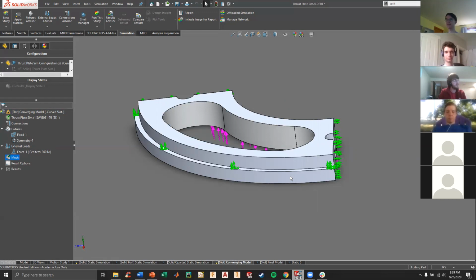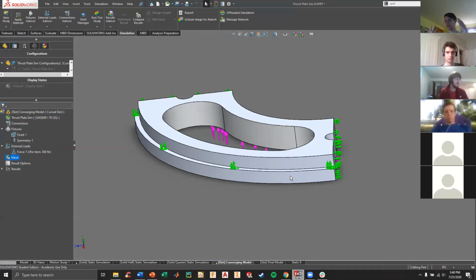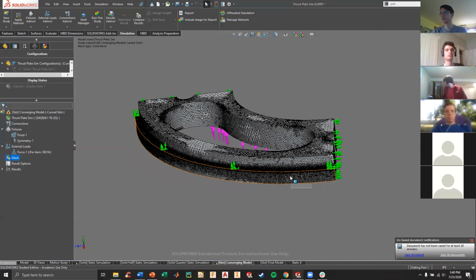There's also P-adaptive, and what P-adaptive does is, without getting too much into the math, because I don't really know what it is either, take this thing called a shape function, which is, there's a shape function for every element in your model. And that shape function is a polynomial of a certain order. Usually, in most cases, 2. Second order polynomial will pretty well describe it.